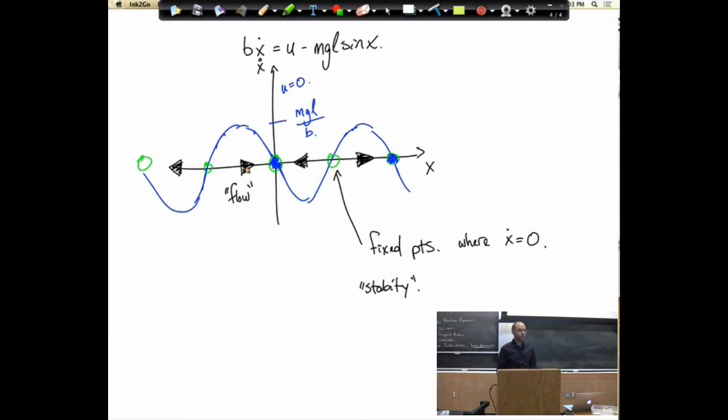There's something else we can already do here, another relatively advanced concept in nonlinear dynamics. So for linear systems, stability is a global property of the system. A linear system is either stable or unstable. We'll talk more about that in a second. Nonlinear systems can have very rich behavior. So this point here is stable, but it's not globally stable. If I were to go all the way over here, I don't come back to this point. It's just got some region of stability, right?